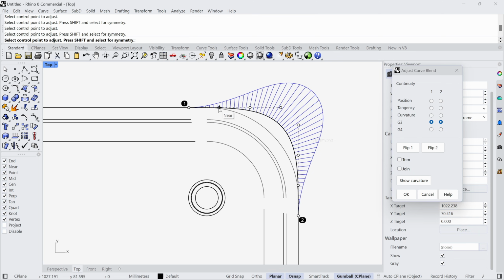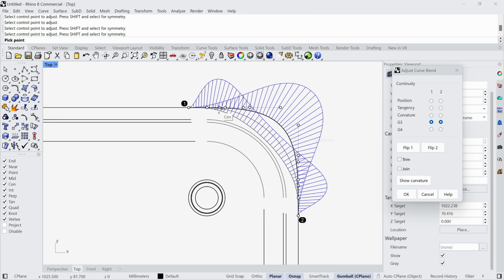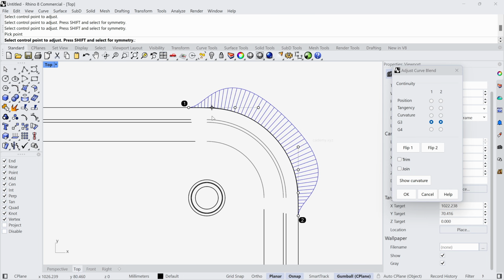So what you can do is press Shift and click on this point and then slowly move it behind or ahead. Now this is going to proportionately move the four points. It's also going to move these points symmetrically. So this way I'm able to mimic the fillet amount quite precisely that we had in terms of the G1 fillet.